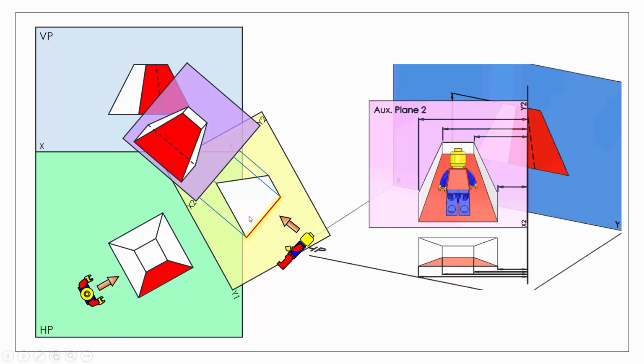So applying our 1-2 rule, you can see that if I'm trying to draw this view here, I count back 1 view, 2 views, I'm dealing with the x2, y2 line. My xy line then, or x1, y1 line, is my previous xy line. So there's my continuation of my lines like so, and I'm taking my distances from the x1, y1 line to my plan view, and I'm transferring them across here. So that's where I get my distances from my second auxiliary. And it would be the same if I took an auxiliary off of that again. I'd be counting back 2 views, 1 xy line.